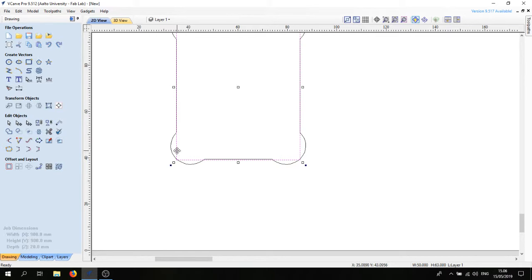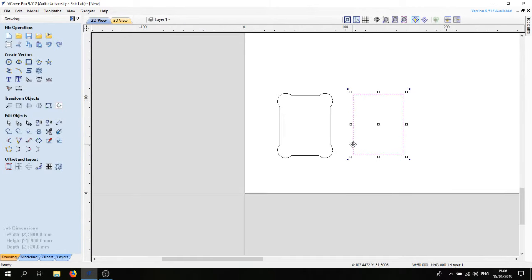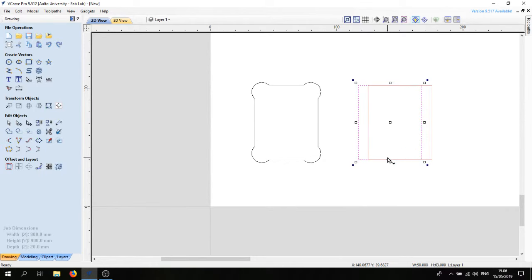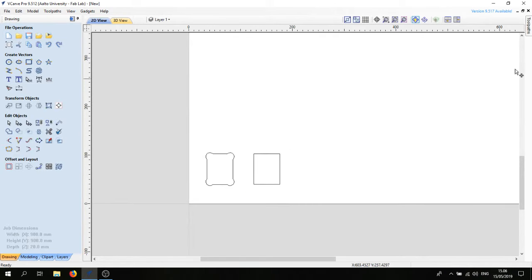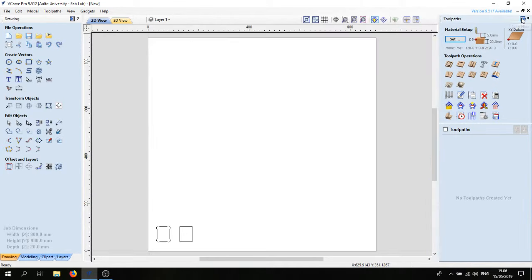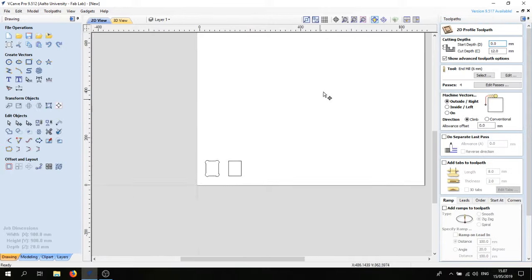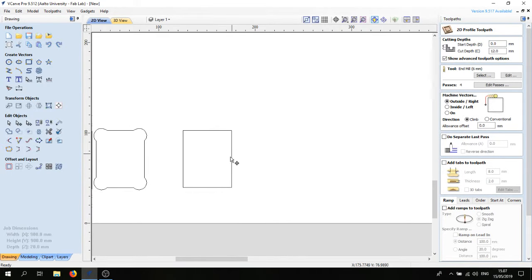So we cut it. It's gonna be funny. So we're gonna cut this square out, and it's gonna be a simple design. We are going to try to put this square into this pocket. How exciting. And now, in order to generate toolpaths, we need to open the toolpath panel over here. So let's snap it to the edge of the window. And let's start with the profile toolpath, or how to cut out a contour, so a piece of it. We want to cut out this square.